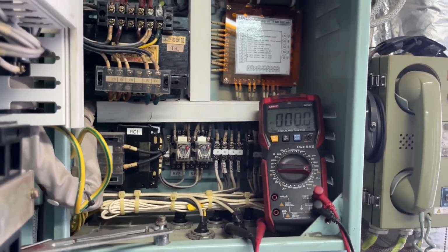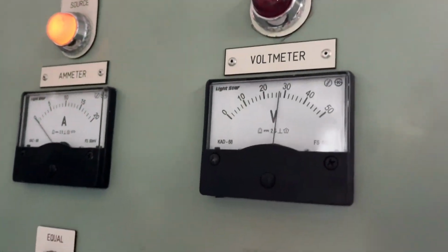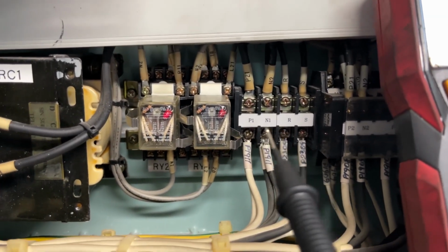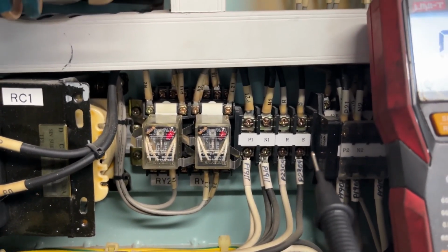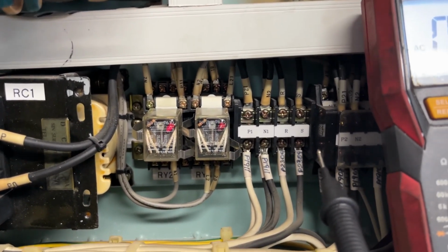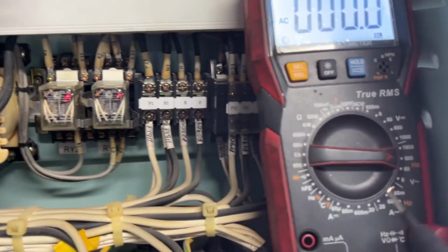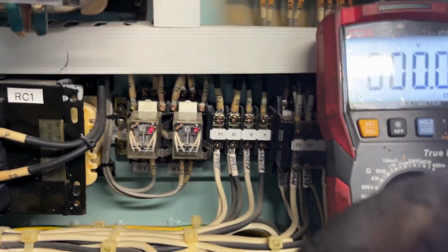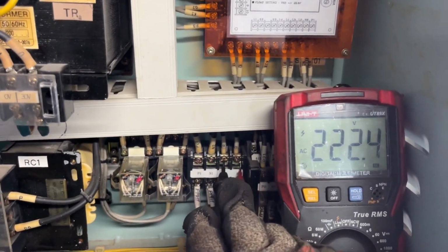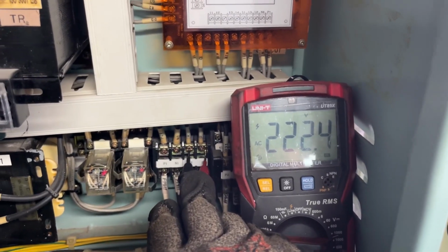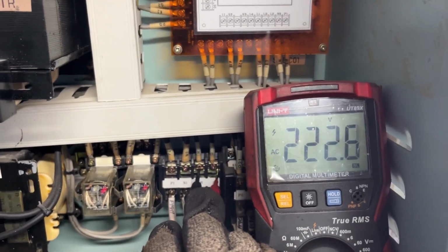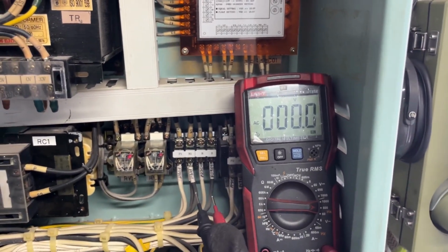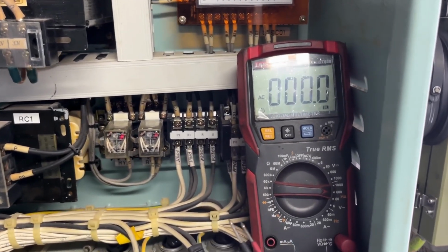So guys, this is a battery charger. This P1 and N1 is going to battery, and this is 24 to 25 volt DC, and this RNS is your 220 volt AC. So right now the selector switch is on 600 volt AC. So I'll measure RNS. So you can see I have connected it to RNS, and the reading is showing 222. Okay, so I have removed it. The value is showing 0.